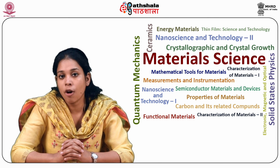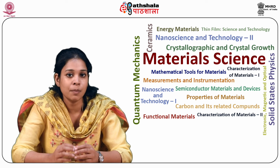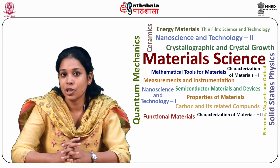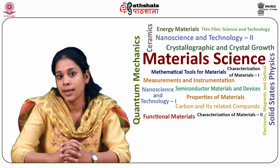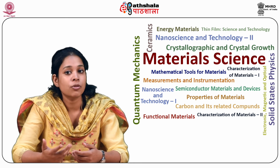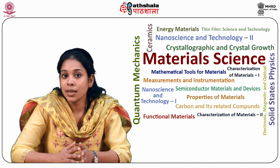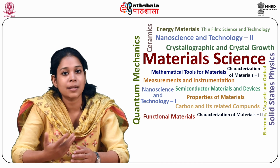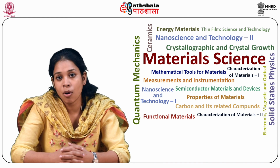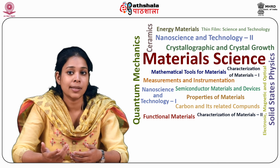The tetragonal phase of pure zirconia can remain stable at room temperature if the particle size is very small. In the module, we read that various factors are responsible for the stabilization of the tetragonal phase below the critical size, which involve lower surface energy of the tetragonal phase, multi-domain structure, and the presence of coherency strains in the particles. This critical particle size is increased to more practical micron levels by alloying with calcium oxide, magnesium oxide, and so on.